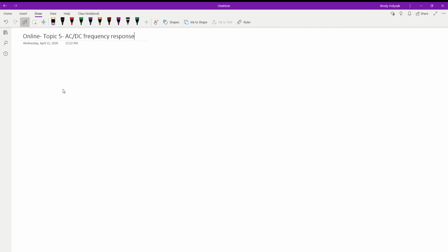So just like what we've been doing before, anytime we add in a capacitor or an inductor, it now has the ability to filter out certain frequencies, and we can see that with these circuits just as well. The big thing is, when we look at them, we have two capacitors in the circuit. If we take a look at the outputs, one of the capacitors is going to drive the low end of our frequency spectrum, and the other one's going to drive the high end. And when we combine these two together, this is going to give us our curve, our Bode plot.